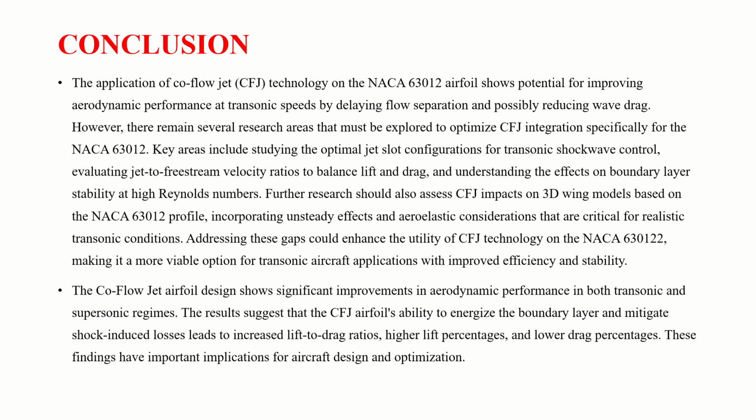Conclusion: application of co-flow jet technology on this particular airfoil potentially improves aerodynamic performance at transonic speeds by delaying flow separation and possibly reducing wave drag. However, there remain several research areas that must be explored to automate CFJ integration, especially for the NACA 63012. Key areas include studying optimized configurations of transonic shock wave control. Using CFJ technology on the NACA 63012 makes it a more viable option for transonic aircraft applications with improved efficiency and stability.